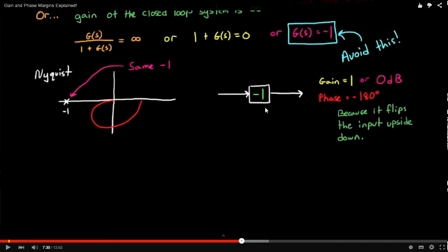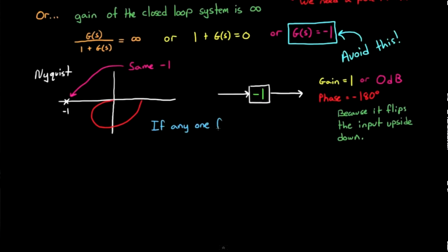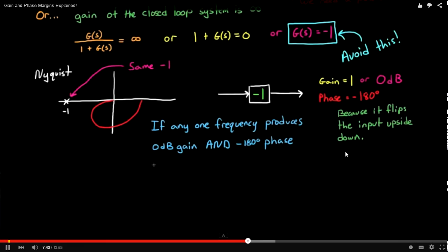So in this case, when it's unstable, your gain isn't amplified, but rather you have a phase of minus 180 degrees. So you're turning the whole system upside down. The -1 point can be represented by 0 dB gain and minus 180 degrees phase. And if any one frequency across the spectrum hits that point, the entire system is unstable. This is why he says that although your gain didn't change, your phase angle shifts totally.